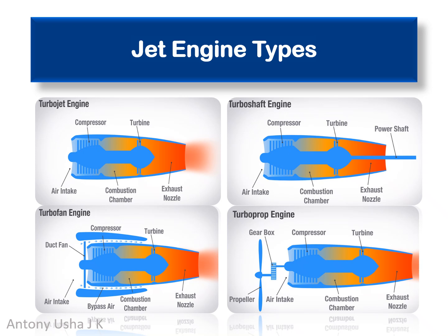First, the turbojet engine. This is the simplest form of jet engine and is primarily designed for high-speed aircraft. Air enters through the intake and is compressed. The compressed air moves into the combustion chamber where fuel is added and ignited. The resulting high temperature exhaust gas expands through a turbine, powering the compressor, and the exhaust nozzle, which produces the thrust.